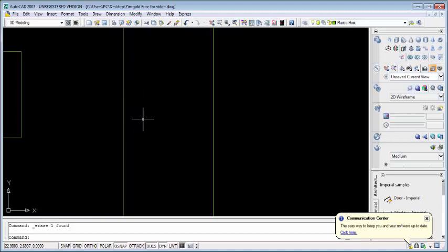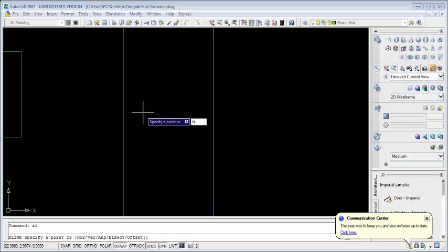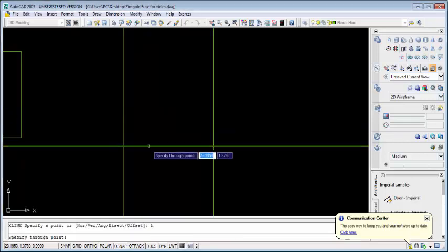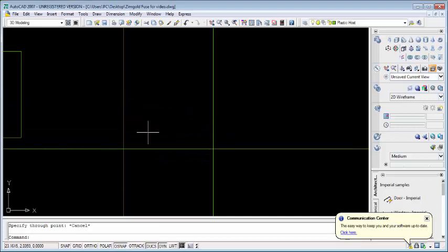Okay, now let me say that is for the vertical sides. XL, that is construction line again. Horizontal, this time around I choose edge for horizontal. I just click anywhere here. I've crossed this place. I'm trying to create a rectangular block. Now I want to offset. O for offset. Hit the space bar.